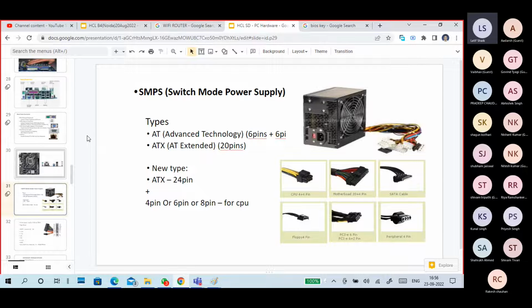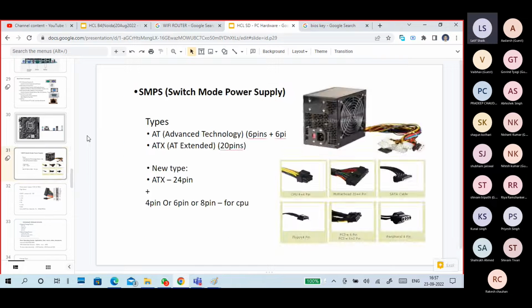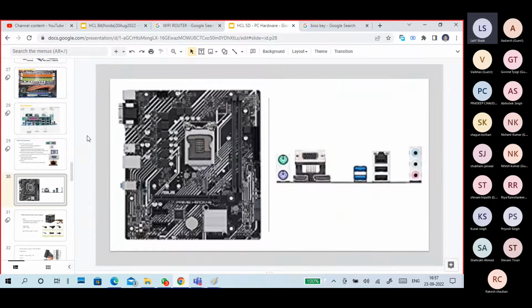Now we are not using floppy disks. Some graphic cards also require additional power supply. Once a graphic card is inserted, it takes power from your motherboard, so SMPS to motherboard, motherboard to graphic card. Sometimes graphic cards also need power directly from the SMPS. At that time you also have to check your SMPS power connections. Sometimes you can use converters also.